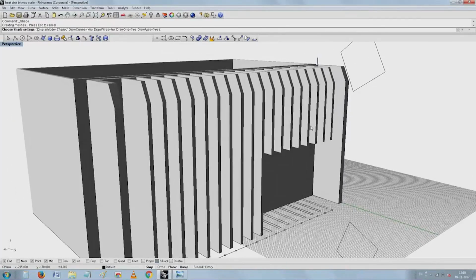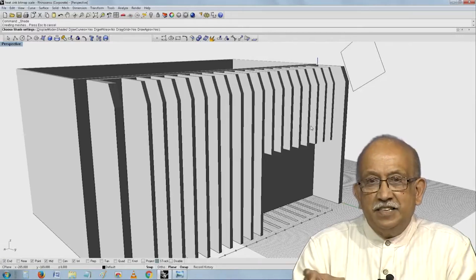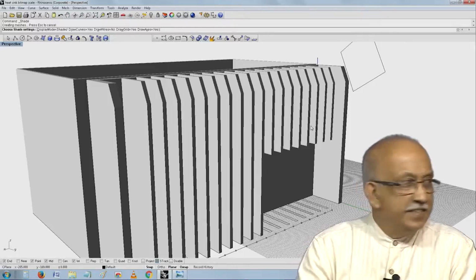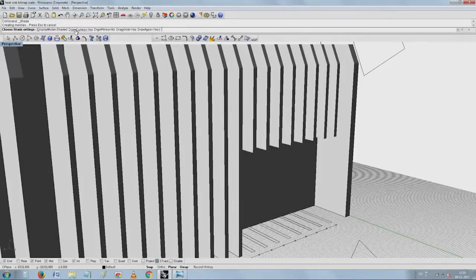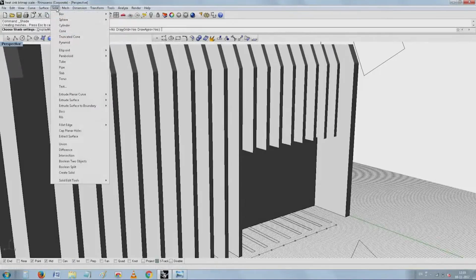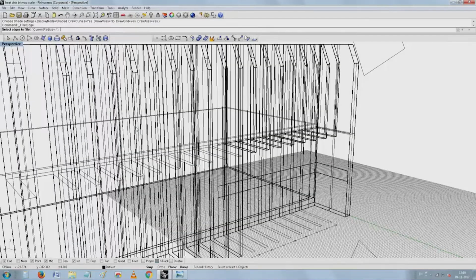See, now I have got a much more presentable and smoother, easier way of managing my profile which I have started. So, this can continue. Otherwise, if you go to solid editing, in solid we also have things like filleting the edge and so on, fillet edge, and then I make a 6 mm fillet.